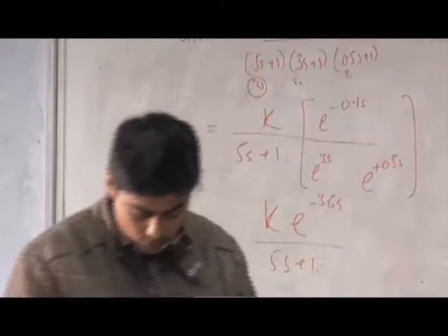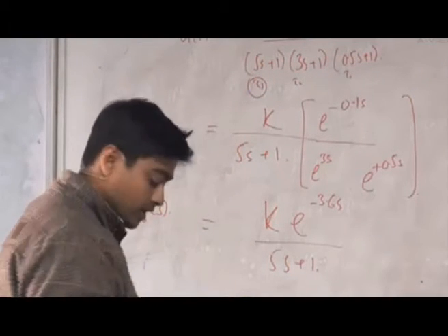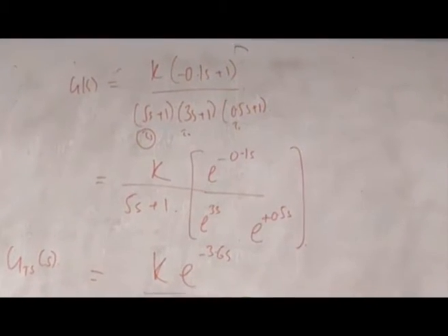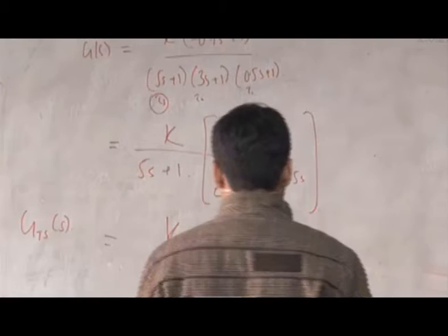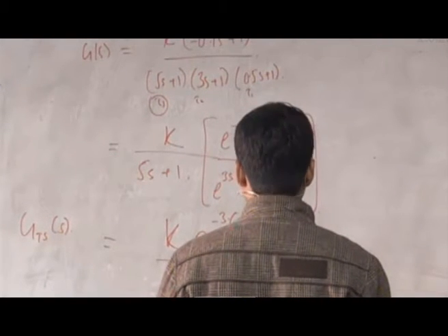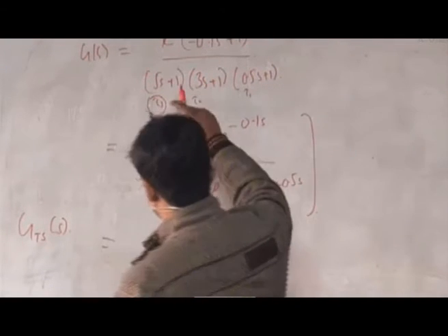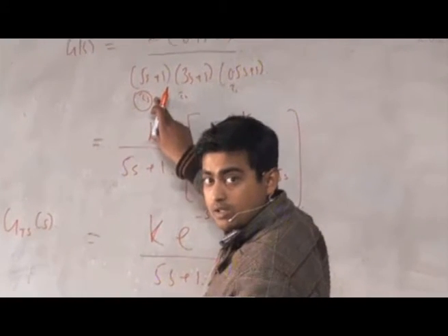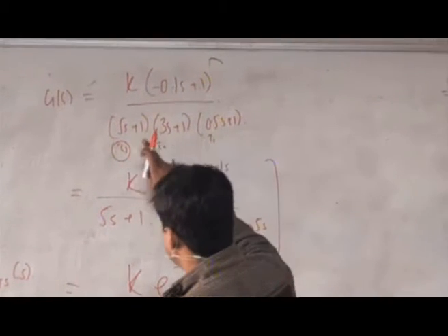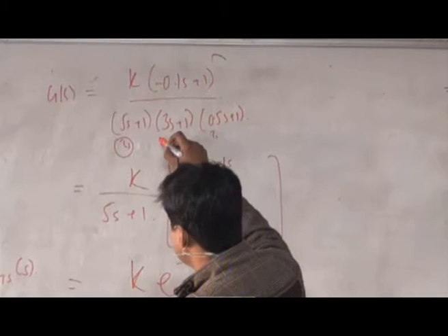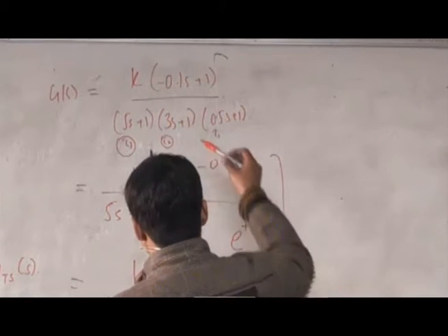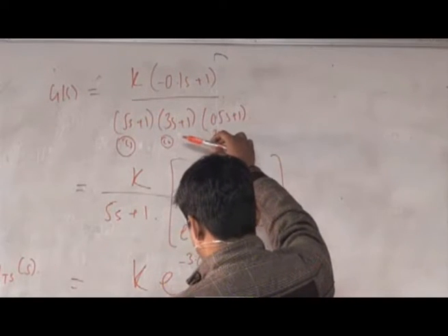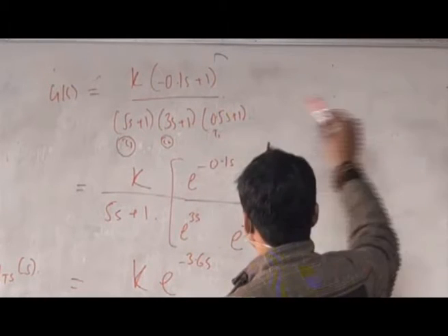Okay, so looking quickly at what the Skogestad half rule says, we are taking the same transfer function. This rule also says to approximate the largest neglected time constant. So this time constant is going to stay in the first order plus dead time (FOPDT) system. The largest neglected time constant is this one now, tau. One half of its value is added to the existing time delay.